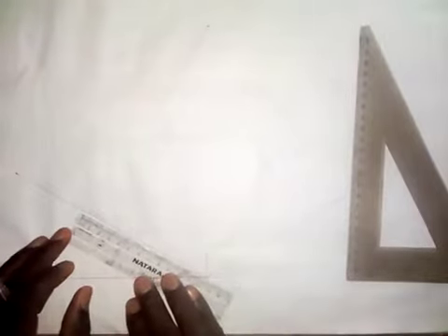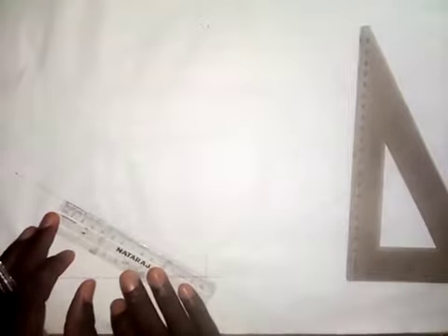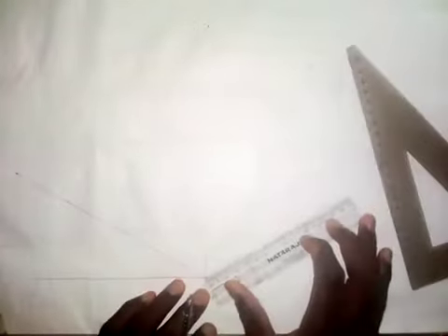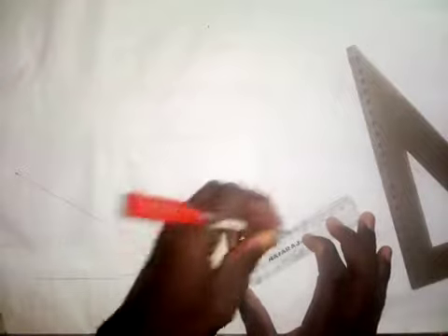Now I will also draw a vertical line at this point here. Don't forget that normally, if it's an isometric drawing that we are asked to produce, they will give us lowest point A or lowest point X, but that is not said here. So this is the lowest point in my drawing. I'll take a measurement here of 140 millimeters, as I've shown you in the main question, that the length on this side is 140, and then on this side I will take 90 millimeters.